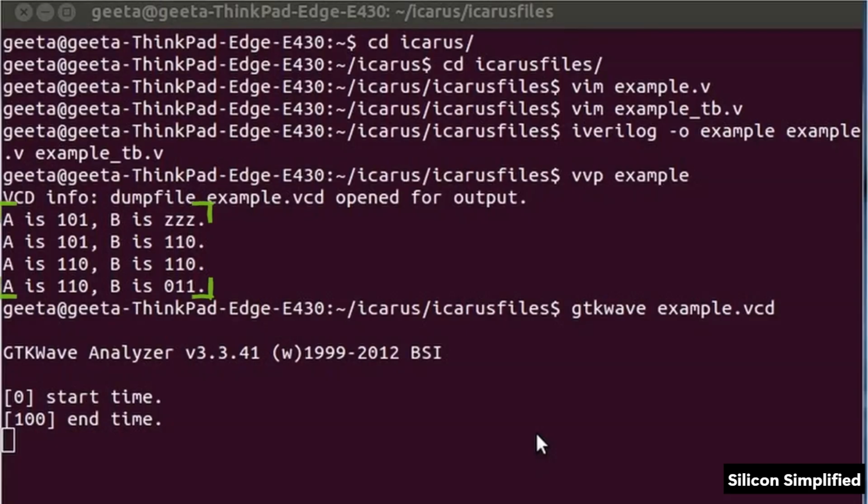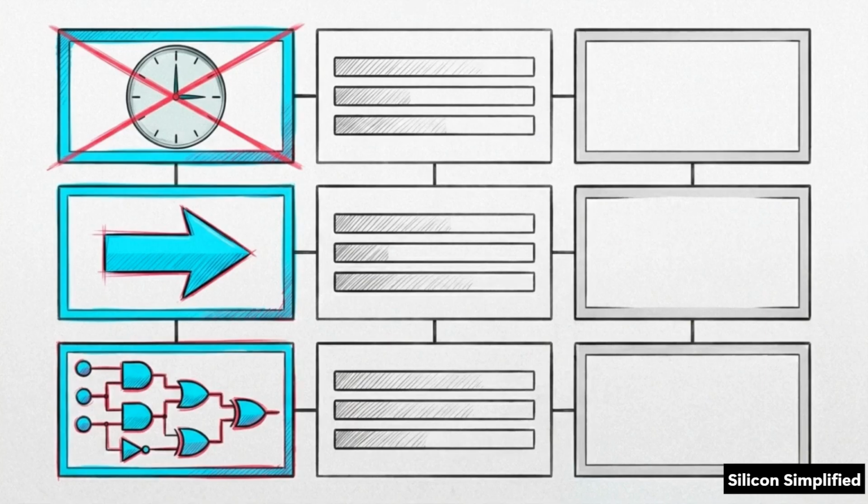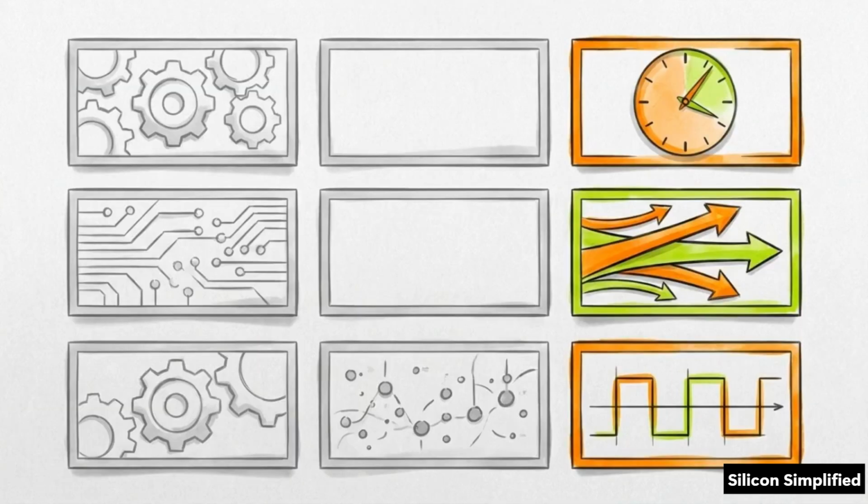The task-driven test bench is pumping data vectors into the compiled logic and generating a VCD dump file to track the resulting waveforms. In practice, functions build the physical chip. Tasks build the virtual laboratory used to test it. This summary table maps out the strict boundaries. Functions execute in 0 time, return a single value, and model combinational logic. Tasks consume time, drive multiple outputs, and model complex behavioral sequences.